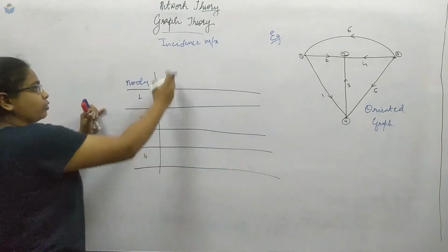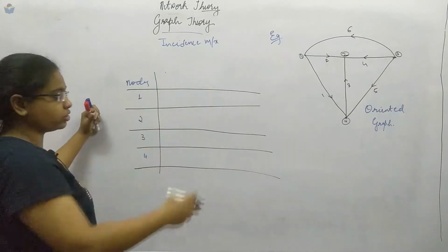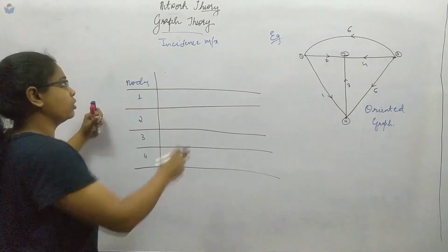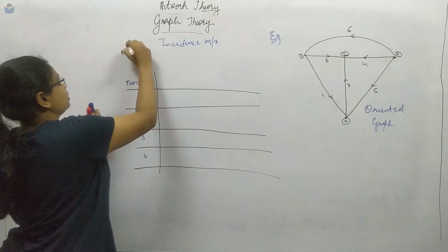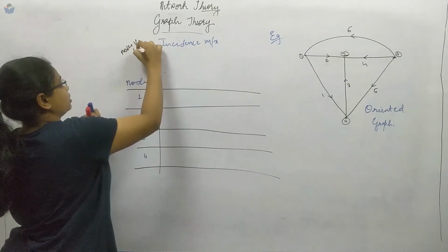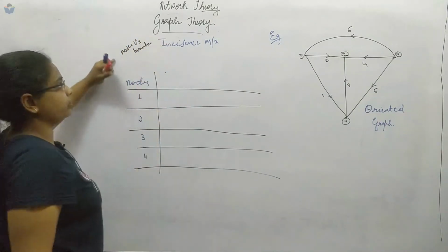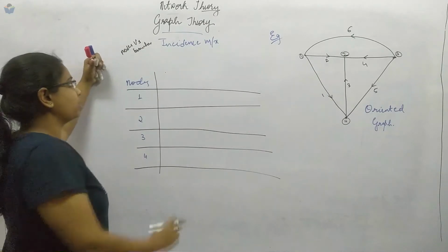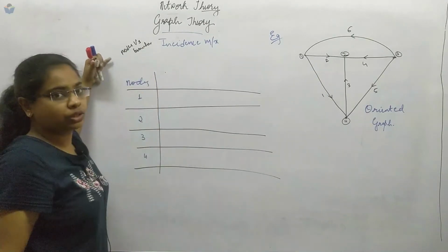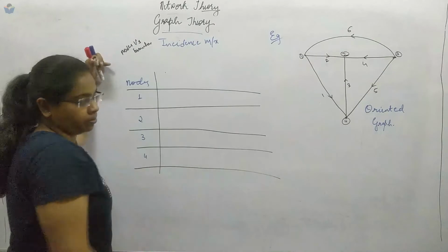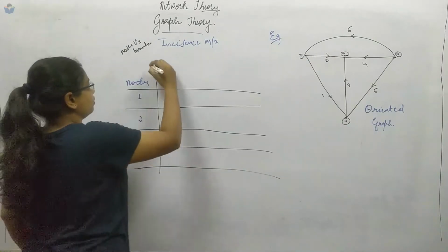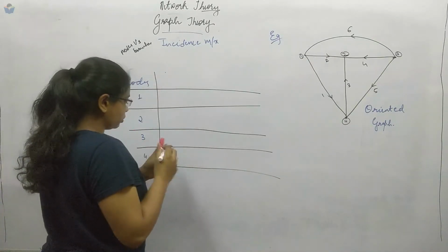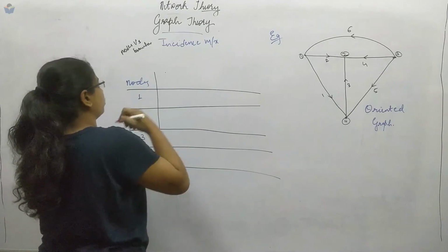Now what we have to fill in this horizontal line is the branches. So keep in mind incidence is nodes versus branches, because further when we do the Cutset or Tieset matrix, it is important which versus which we are going to draw the matrix for. So horizontally it will be the number of branches.